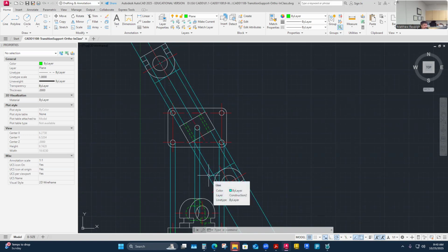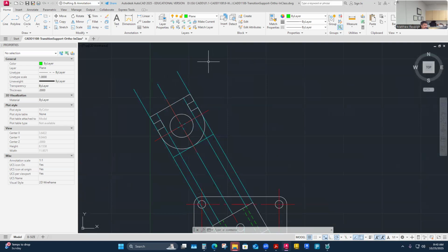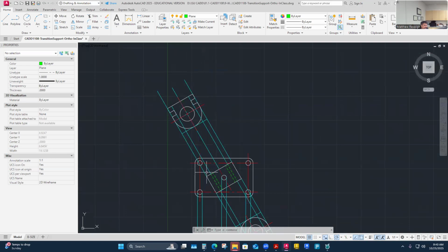I've chosen just to do it as, it's only a partial auxiliary view of that, right? I haven't detailed the base, which would all be foreshortened in my view if I projected all this over and actually drew the full auxiliary view. It's definitely got a lot more detailing to do, and it wouldn't be stuff that I would be using for dimensional purposes anyway. It would just be for maybe visual clarity. And so where I get really shorthand is definitely CAD, and it's a little bit more labor intensive to build that out manually for nothing more than just no dimensionability, just viewing clarity.